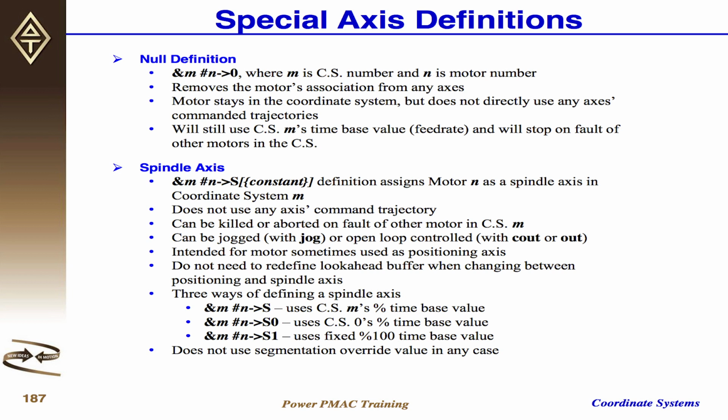Very useful for debugging. If you're setting up a system for the first time and you're afraid of collisions, you might run it at 10% time base or something like that, just so everything is moving a lot slower. And if you have a collision, or if you see an impending collision, you have more time to stop it. Very useful for debugging or original system setup if you have a large machine.